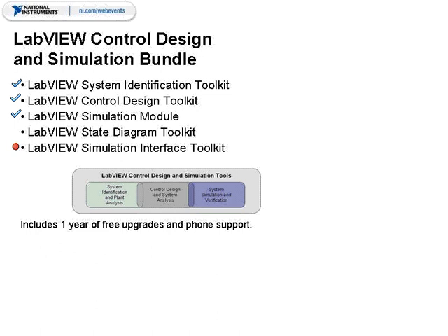To enable running Simulink models directly on LabVIEW real-time targets, the Simulation Interface Toolkit also allows you to use the MathWorks Real-Time Workshop tool to automatically generate a DLL from a Simulink model and then can be embedded on a LabVIEW real-time implementation that automatically calls that Simulink model to implement the model in real time, again for either implementation, rapid control prototyping, or hardware-in-the-loop simulation.